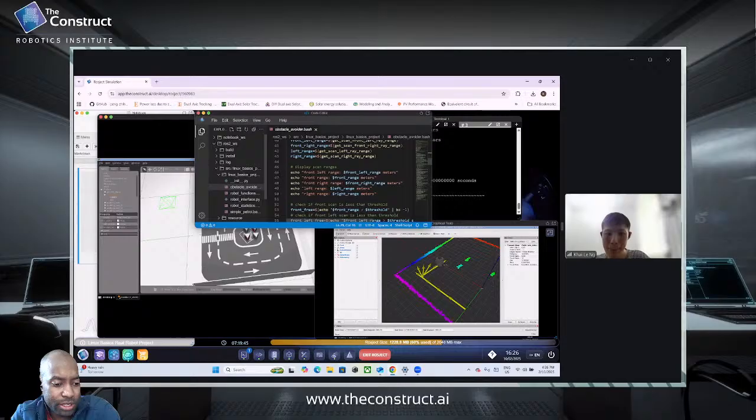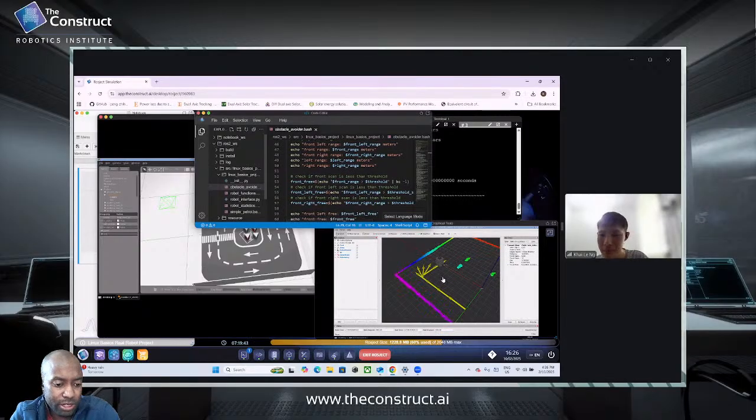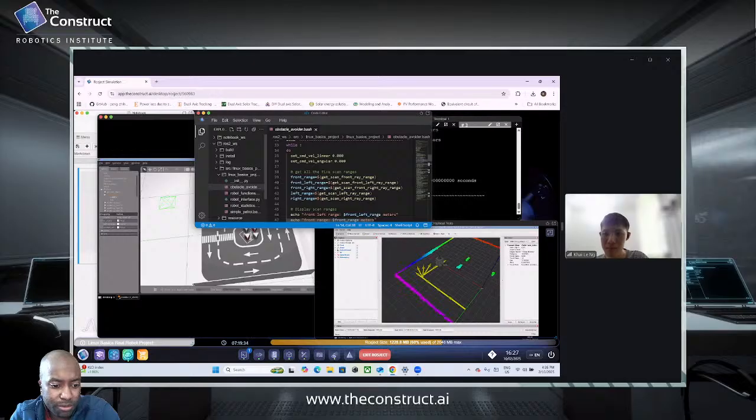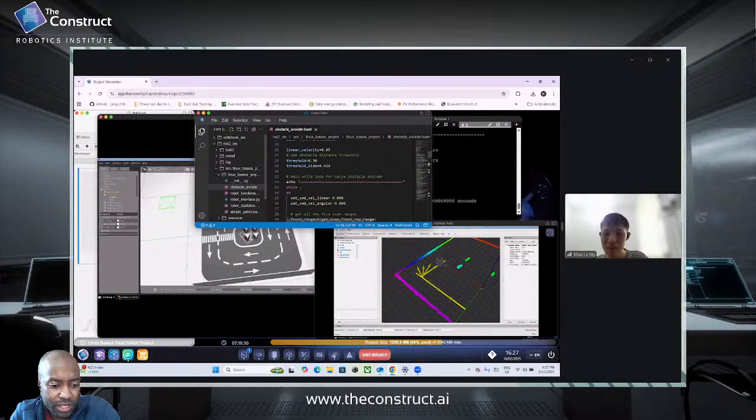Okay. So this makes a lot more logical sense to me. If you say that you set this value based on the performance of the real robot, then it makes sense, because maybe you were encountering some lag. So by the time you set your parameter to 0, it will have moved a very significant distance to a point that is too close to the wall, right? So that is the reason I can accept. But for the simulation, I really find no reason for you to have done that. That's why the simulation is different from the real robot. But yeah, it's alright.